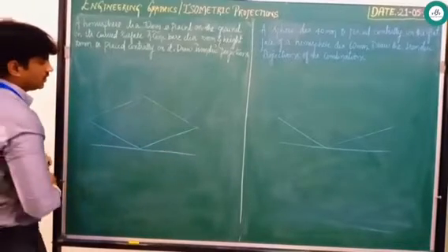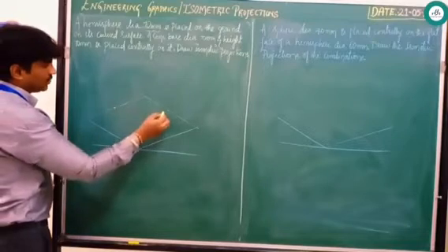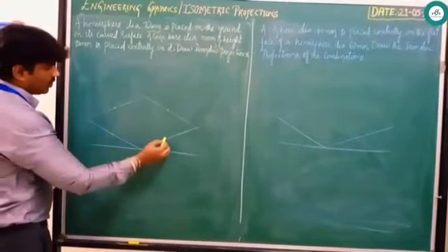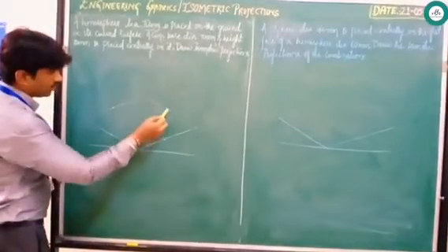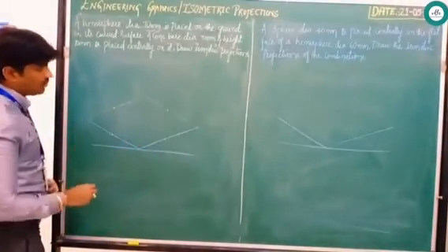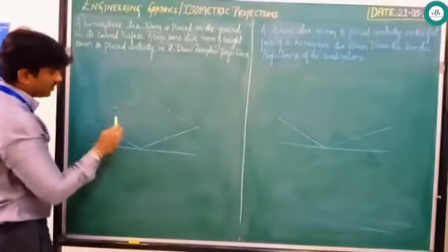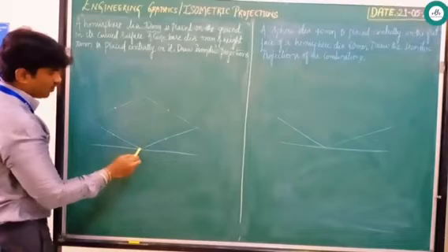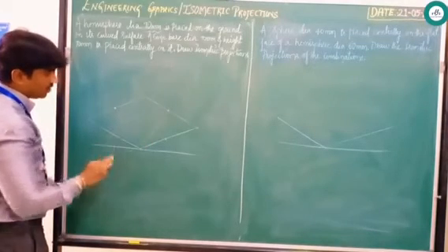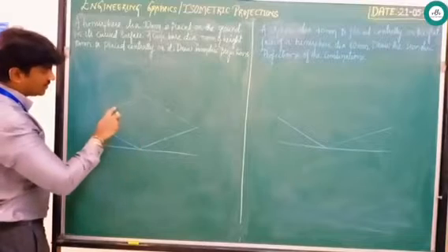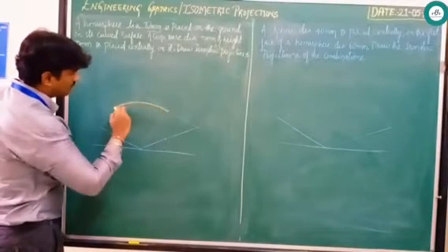After drawing this, how to identify the center? You know that. Take a midpoint of this. After drawing this, if you join these lines, you will get a midpoint. Before that, how to draw the curved surface here? Join these 2 points to this particular point. So join this way. Next, with this as a center, this as a radius, draw this arc.